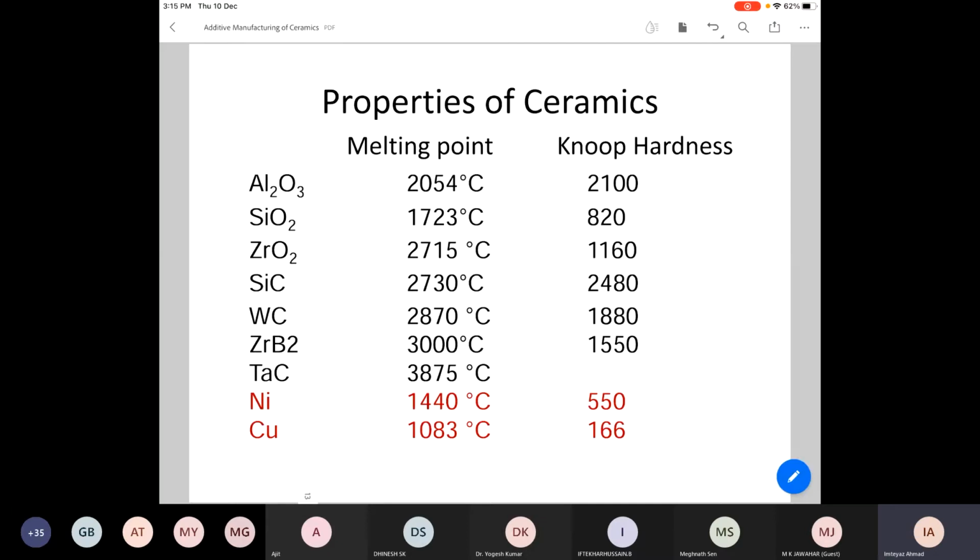The reason is that you need heating elements. And these heating elements are either carbon or zirconia. They can give you this kind of temperature. They can withstand that temperature. But now these get oxidized also. To protect the heating element, you need an inert environment. So now maintaining the heating element becomes another problem for you. So that's the reason. And also they are very tough. If you pour them from the melt, they solidify, they crack. The reason is they cannot take thermal gradient. So these are the reasons.